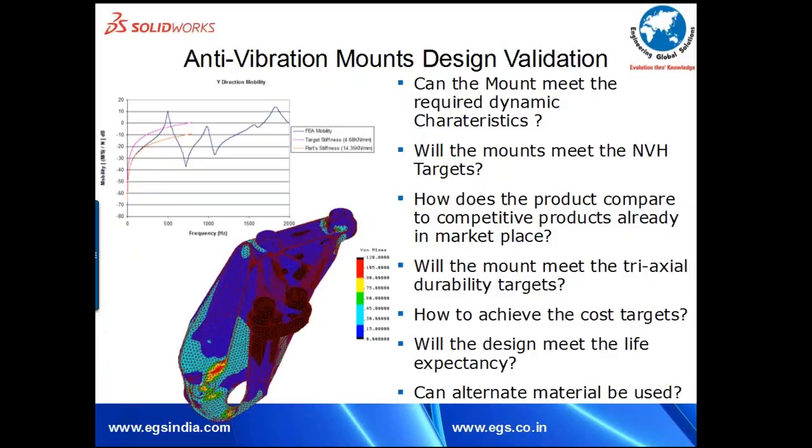Why is it high cycle and why is it low cycle? The high cycle is in the elastic zone. The low cycle is in the elastoplastic zone. So in other words, if you are doing accelerated durability testing in your lab and you are saying 5,000 cycles of this is equivalent to 3 years of warranty, then you know where you are. The trick is to establish the reliability model between this number of cycles versus the warranty that you have provided.